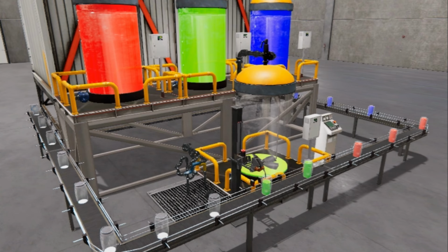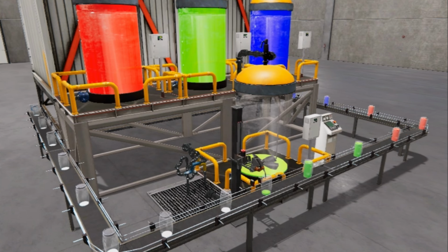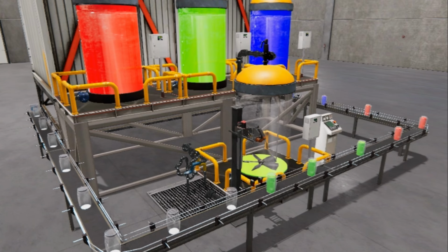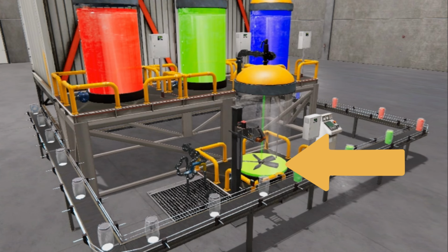If the mixing tank is less than 100, the number of filled bottles has been accomplished. The mixing tank will then need to be cleaned and purged. We will clean the mixing tank by turning on the output and ensuring the volume goes to 0. We will then turn the mixing tank output off and turn the mixing tank input on.